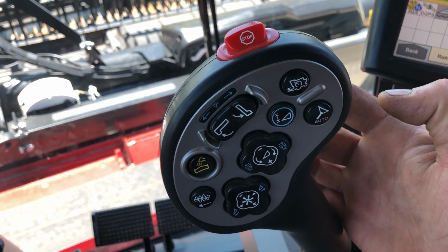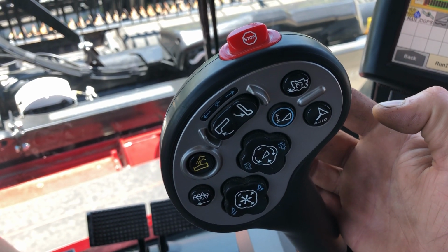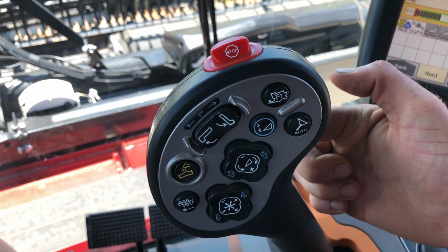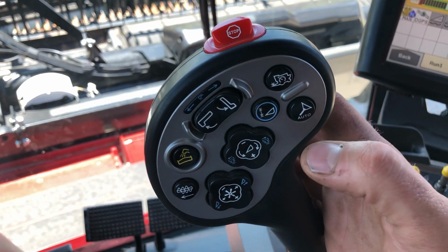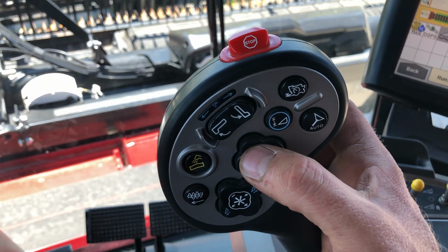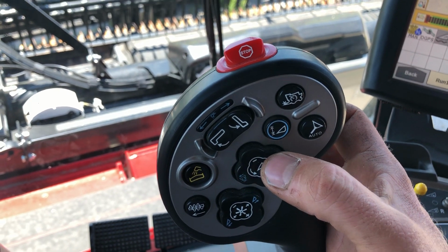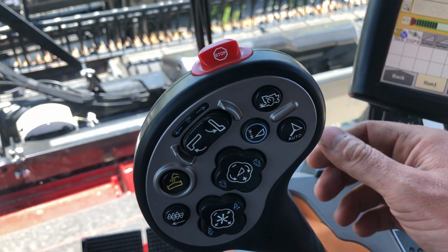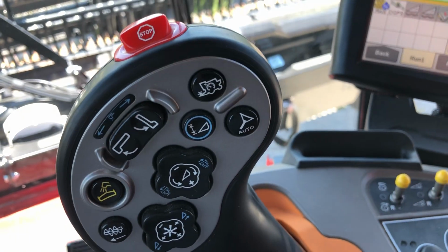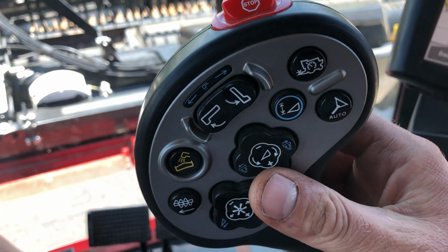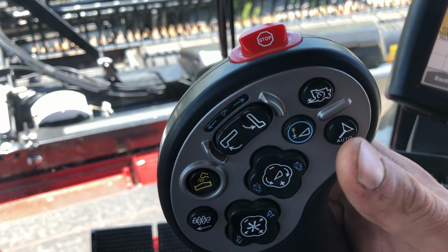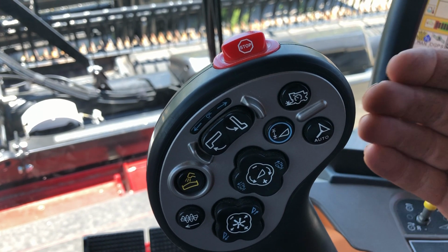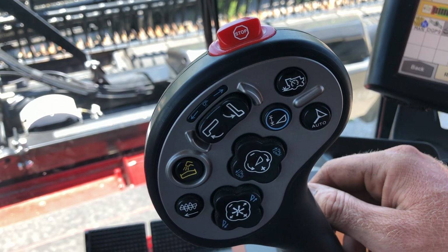Now with feed rate, we can also adjust that target speed a little bit. To do that, we've got our shift button up on the front of the multifunction handle. If we hold that and do our hitter up down, it will adjust my feed rate target. So if feed rate is acting a little bit sluggish for you, press and hold that button, bump the plus once or twice, and see if it responds better and acts like you want then.